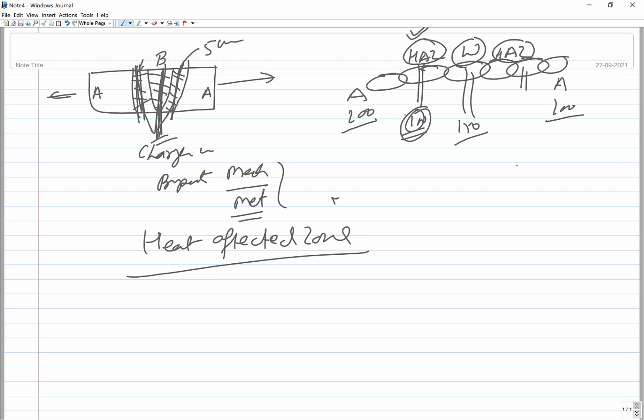As I said, in the metallurgical continuity approach of developing the joining, this gives either a joint strength of 100% or it can be lower also. If it is free from defects, most of the time it offers good joint strength. The second, the problem with mechanical joining or mechanical interlocking, is that you have to add metal while developing a joint in the form of nuts and bolts.